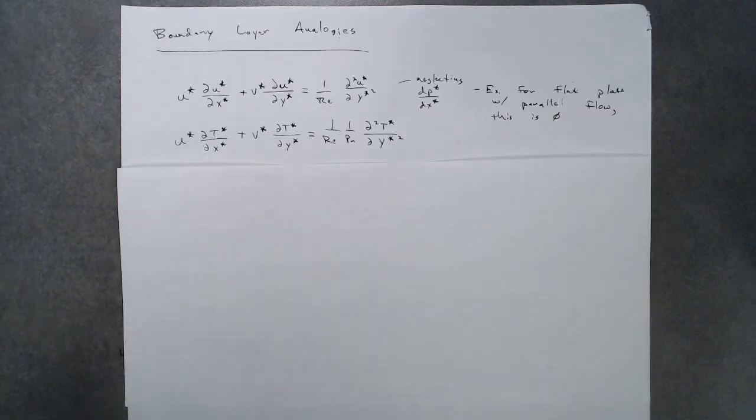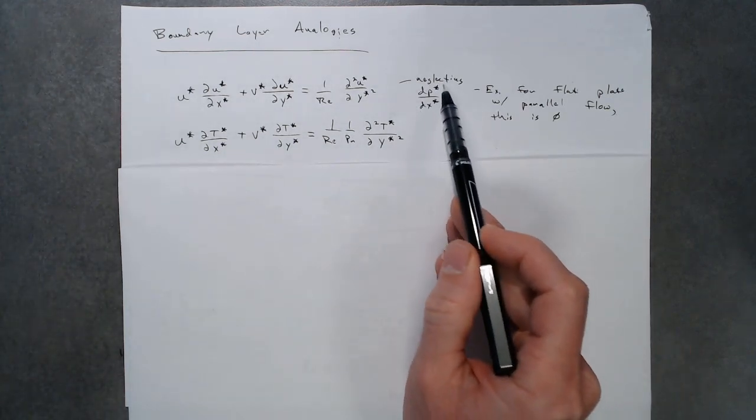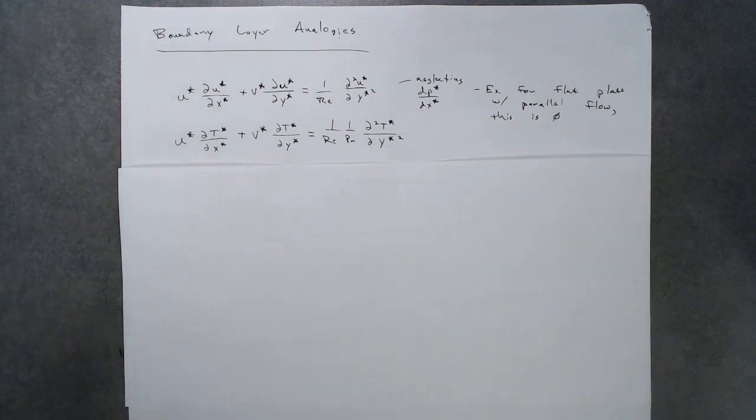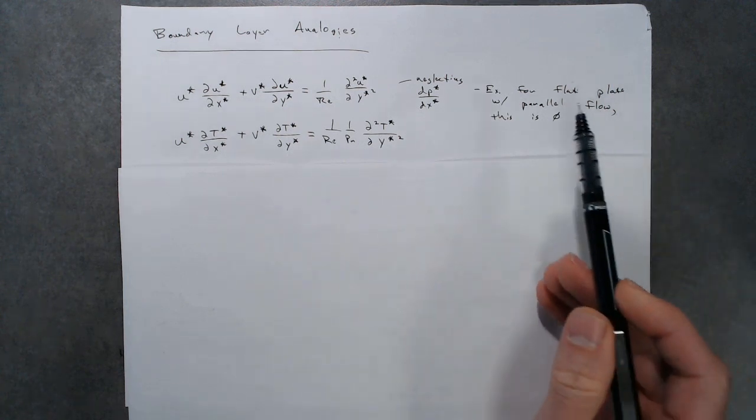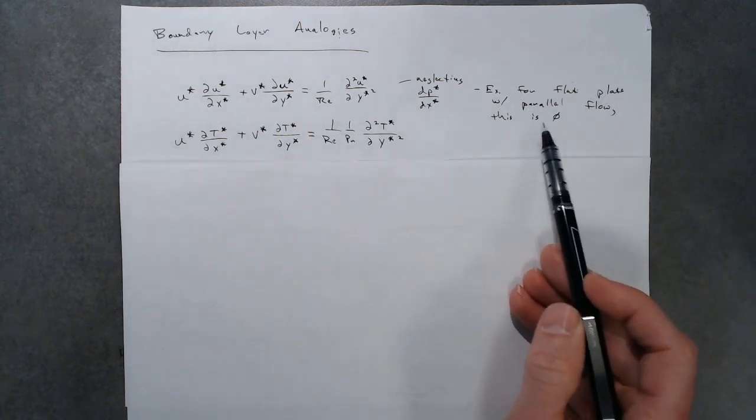So we looked at the non-dimensionalization of the three boundary layer equations, and we pointed out before that once we non-dimensionalize them, the equations themselves look similar, specifically the momentum and the thermal energy equation. Particularly if we neglect this change in pressure, this pressure gradient, which for example, for a flow over a flat plate in parallel flow, is explicitly zero.